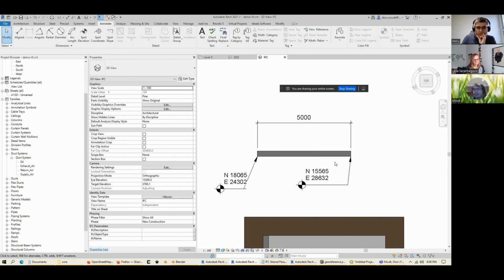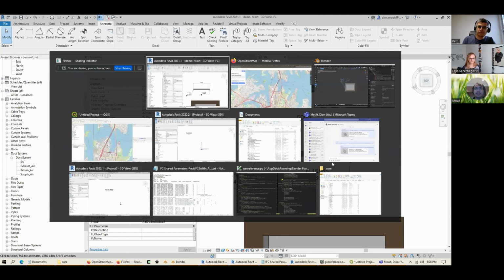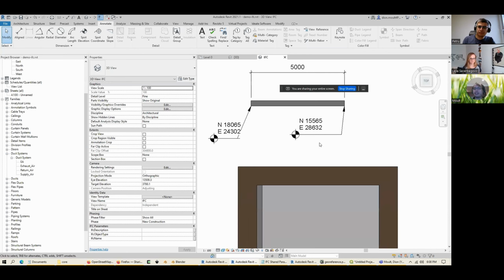Because on a small site, even though the scale factor changes, it can be approximated to a constant. And when I say small site, the small site is defined by the Building Smart georeference experts as 1 kilometer. So if your site goes past 1 kilometer, then it's no longer considered small, and you cannot approximate that scale factor to be a constant. Whereas if you are dealing with a small site, you will get a constant.